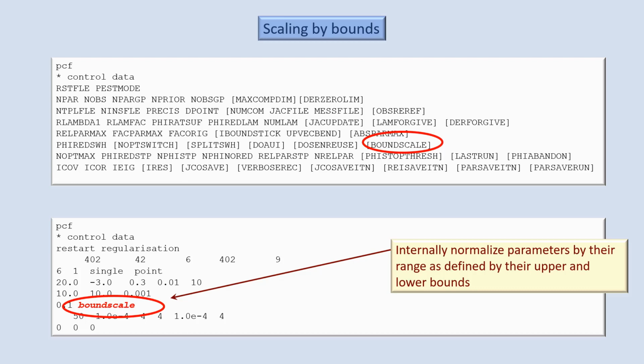If you do set the bound scale parameter in this manner, however, you must be careful to ensure that the bounds that you provide to parameters in the parameter data section of the PEST control file do in fact reflect the innate prior variability of every parameter. Sometimes I set the bounds very low and very high, virtually dispensing with the use of bounds, so parameters can go where PEST tells them to, because there may be a message about where PEST wants a parameter to go.